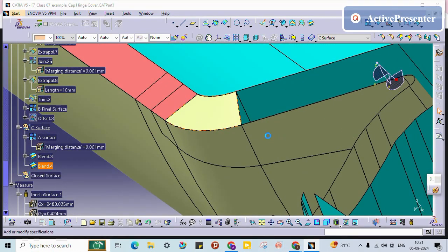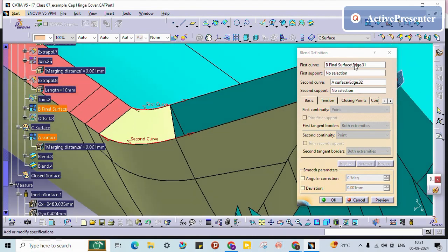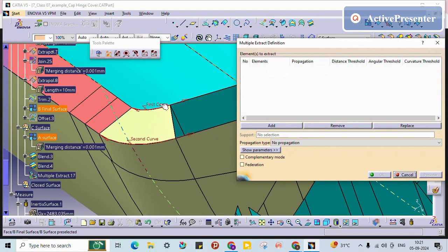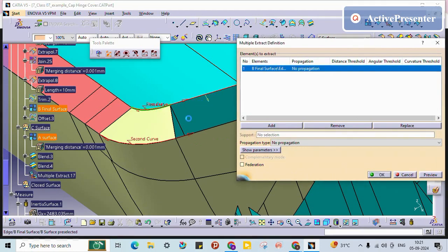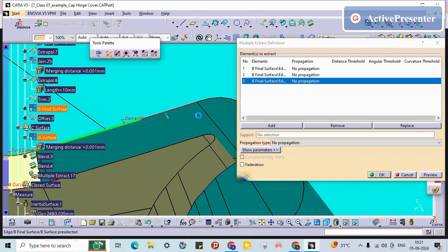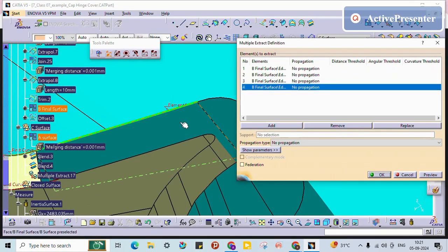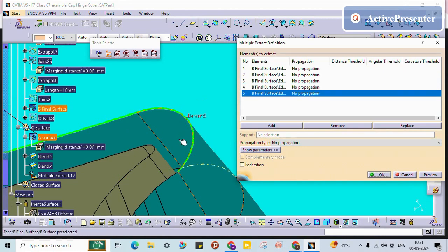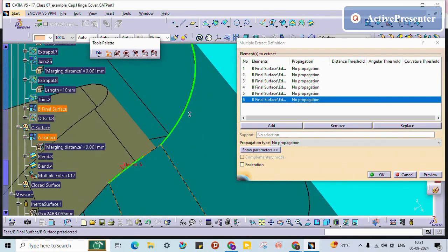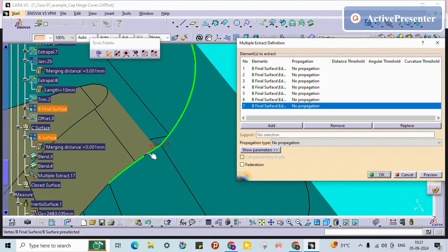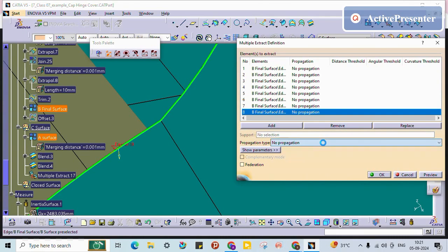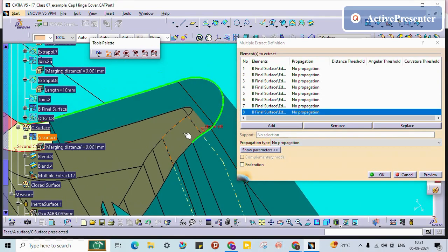Instead of this, what I will do is, till this edge, if you are giving it, it will come smooth. If I am trying to take this surface till here, instead of selecting like this, you can give the tangent continuity, and otherwise you can create the boundary also.